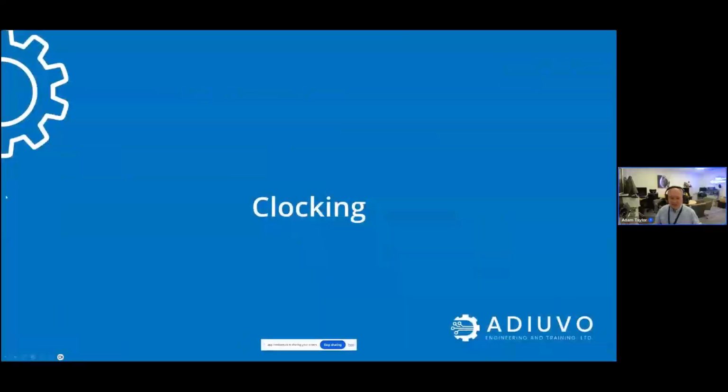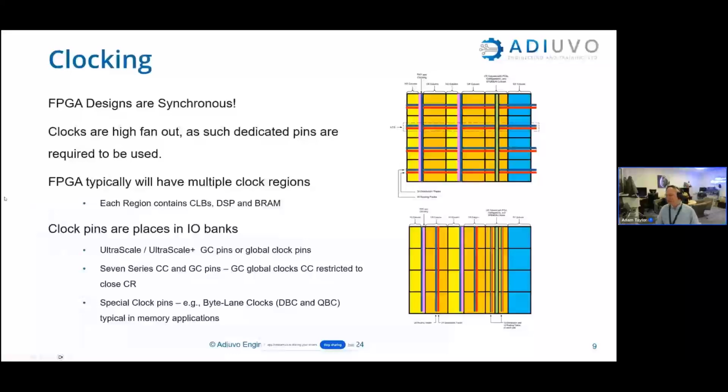So let's start at the beginning and talk a little bit about clocks in our FPGA design. Obviously we want to design our FPGAs to be synchronous, which means we need to leverage the clocks that are coming into the FPGA. Now, we don't just use the clocks on any old pin on the FPGA. We want to use them on dedicated pins because they're high fan out. And obviously the manufacturers of these devices have thought about this, and they put clocking resources within the FPGA that we can use to help us get through the design and make sure that we can achieve timing easily.